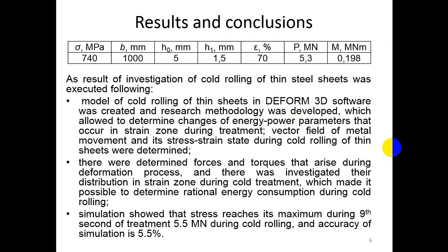Micro cracks and microfibers may appear on sheets and rolling tools. Reduction of the deformation degree up to 45% leads to decrease of strength and hardness of metal. Sheet is able to deform plastically under load during operation.